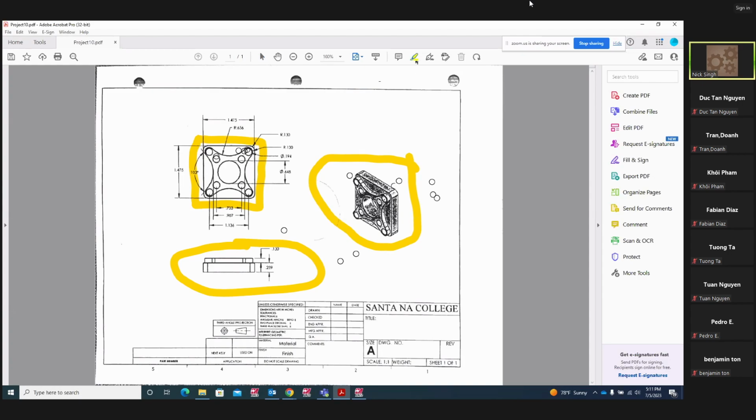Whatever we have done on the last 7-8 projects, guys, we have done the lathe part with the standard lathe operations, which is facing, OD turning, OD rough and finish, OD grooving, OD thread, ID grooving, ID thread. So that was regular, simple, standard operations on the lathe.